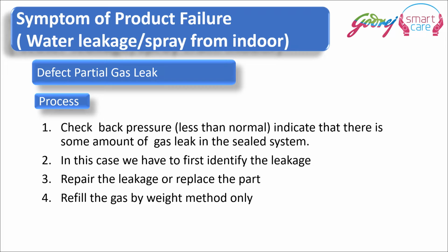Here what we have to do is first locate the leak from the sealed system. We have to mend, or braze, or plug that leakage, and then we have to vacuum the system. We have to refill the gas by the weight method only.